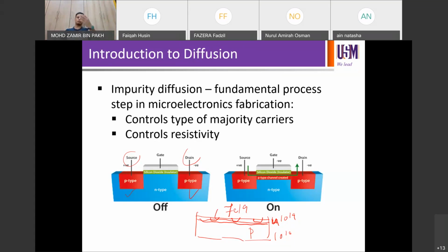If you discuss solar cell, you will understand why we need the heavily doped region. It improves the contact resistance between the top n-type emitter and the metal contacts later on, so that you can easily get ohmic contact formation, less resistive, and reduce the overall series resistance of the emitter and the emitter to the contact in order to improve solar cell performance.